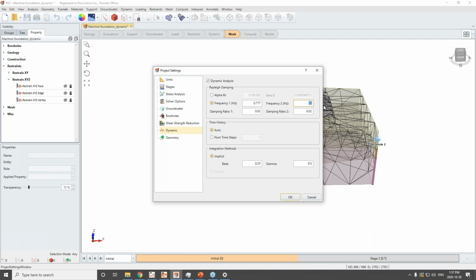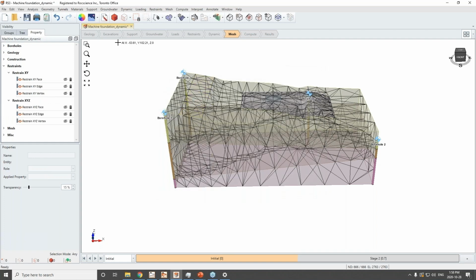So in our case, the ratio is 5, the frequency of the motion, divided by 0.77, the natural frequency of the model. We got 6.47, and the closest odd number is 7. We multiply 7 by 0.77, and we got 5.39. And we just use the default value of 2% damping ratio right here. Click OK.